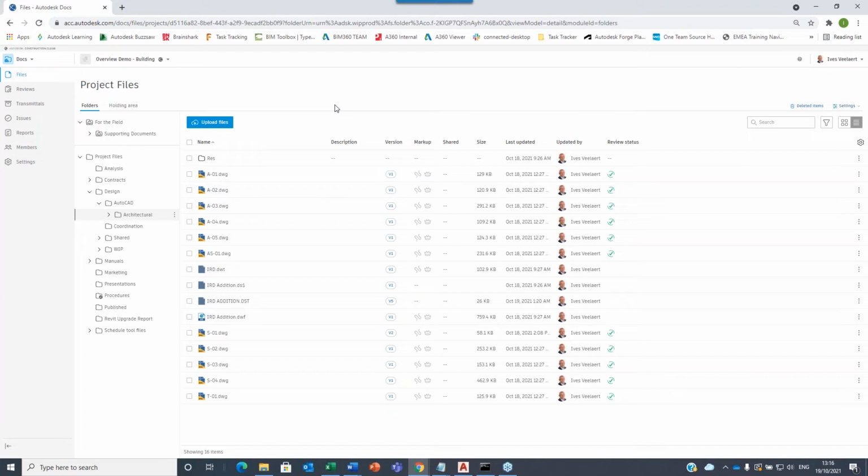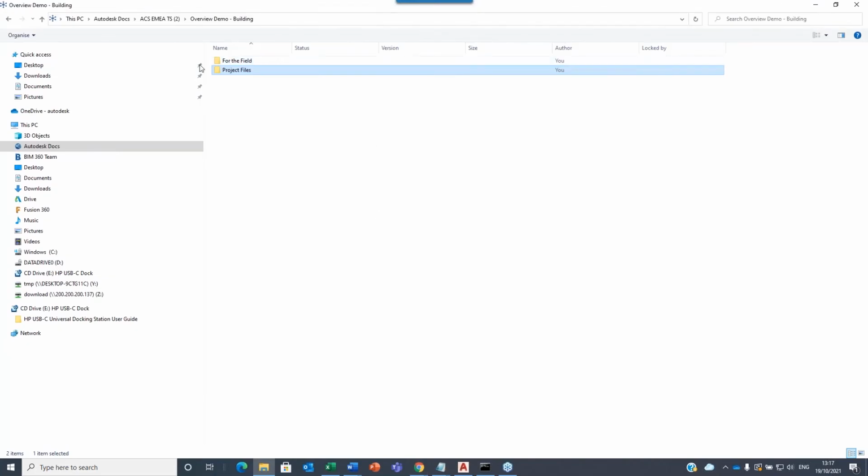Now, how do we connect AutoCAD, for instance, to this system? It depends a little bit on what type of design tool you're using. So we're going to focus on AutoCAD today. Let me just say that for a basic AutoCAD, vanilla AutoCAD, all you need is to install this thing called the desktop connector. The desktop connector is nothing more than, probably most of you are using Dropbox or Box or SharePoint or Teams or whatever to communicate, and all of these have a syncing folder or a syncing environment to the cloud. That's effectively what we have here, and that's what we call desktop connector.